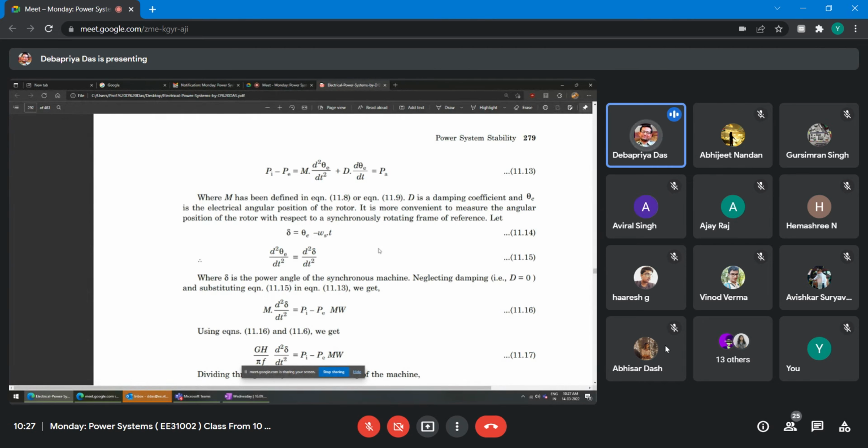Actually, in the laboratory, 0 to 360 degrees is everything marked, and you have to mark the reference by chalk, right? When you press the stroboscope, it is fixed, and when you increase the load, you can check the difference of the angle, right? You might have seen it online, I'm not sure, but in the laboratory, when you are doing this, at that time you will see that.